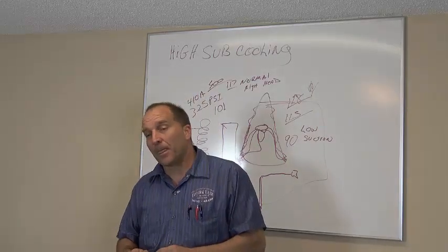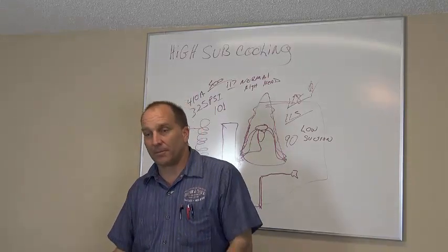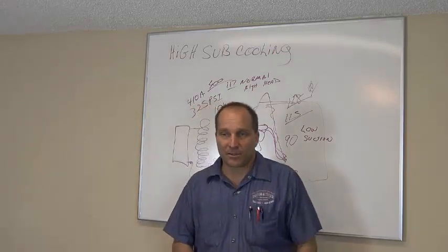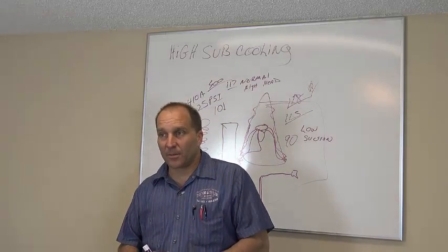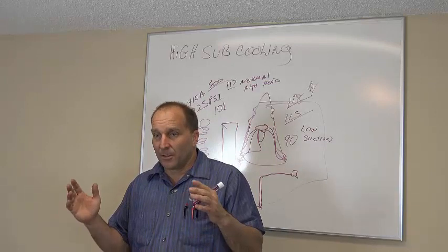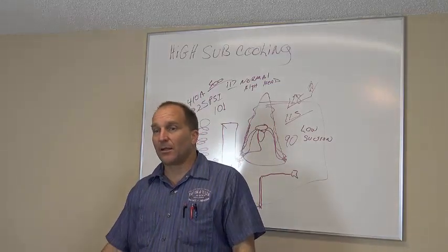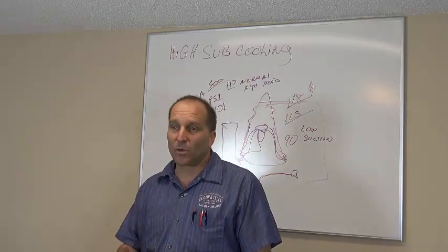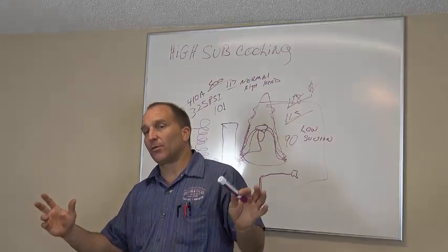You go put your gauges on the system, and you're charging this system up for the first time. Let's just say it's 80 degrees in the house, so it's not extremely hot, and it's 85 outside. The first thing I want you to do is put your gauges on the system, start putting refrigerant in, have your clamps on there, run that head pressure up, and watch your subcooling. Bring your subcooling up to, let's just say, 10 degrees, and then stop putting refrigerant in it.